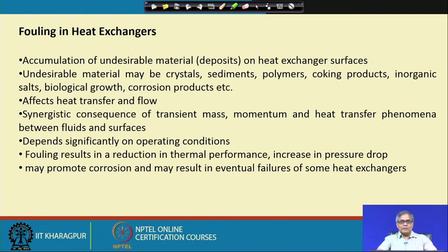This may even, which has not been mentioned over here, affect the performance of the downstream equipment. If there is some fouling or deposition in the heat exchanger, some of the deposited material can get dislodged and pass with the liquid to the downstream component. So, that way it may affect, and it may also affect because the downstream equipment may not get the fluid at the required temperature and at the required flow rate. So, fouling is important.